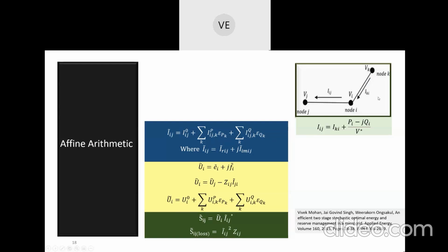So throughout the execution of load flow, wherever addition, subtraction, multiplication, whatever comes, it is done using intervals. We are not using two different values, we are using two different ranges. It's not like A into B. It's interval of A, which is A lower bar, A upper bar, into interval of B, which is B lower bar, B upper bar. So this is interval arithmetic.